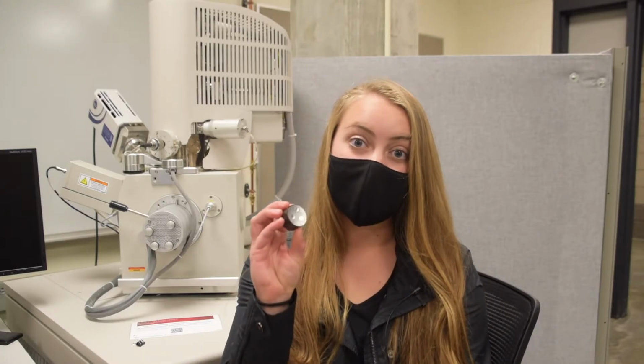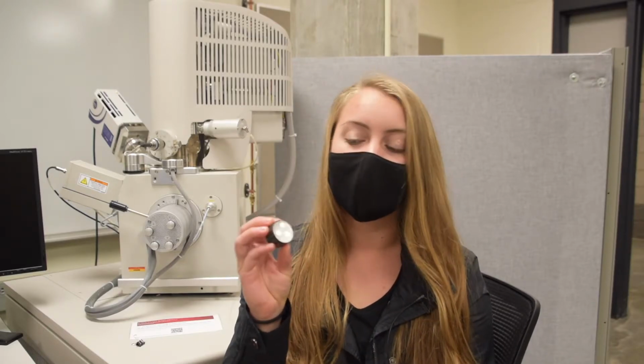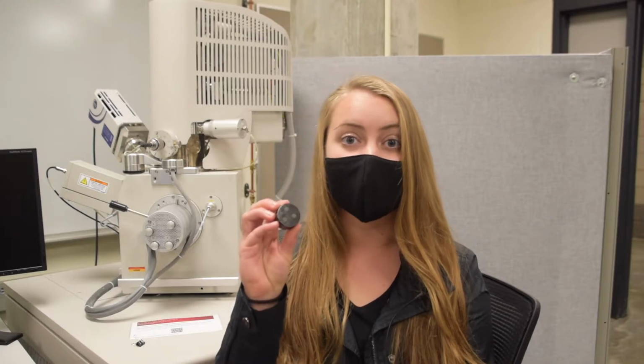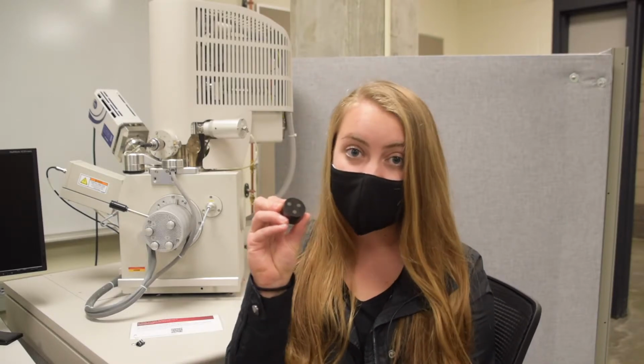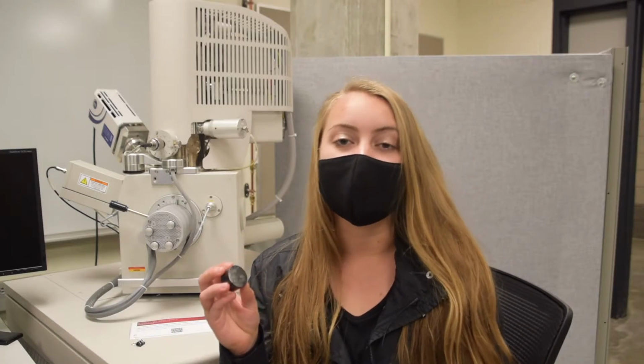Hello, my name is Maddie Harrington. I'm an undergraduate researcher for Dr. Collins' group. I'm working mostly with characterizing additively manufactured titanium alloys. This is an example of one of the samples we have, and this is an alloy called 5553. So this is a cross-section of titanium, and what we do is we stick this into the SEM and look at the microstructure up close to understand its properties and behavior.